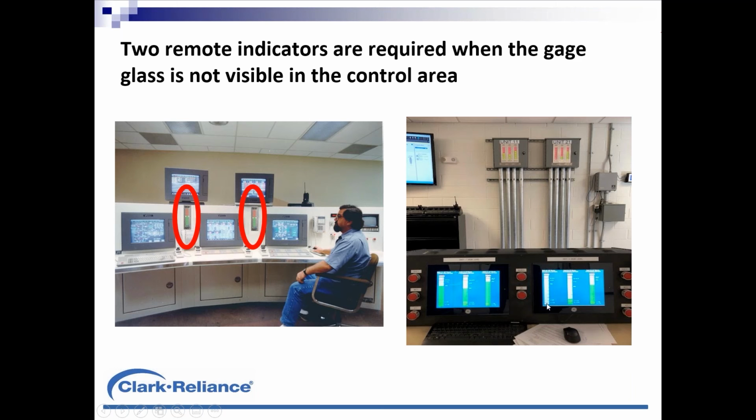Now, this 4th drum over from the left is empty, showing dry, but that unit was out of service at the moment we took this photo. But again, if I were in that operator's chair, I got 2 different technologies for each drum, and they're all reading comparably. So here again, high confidence in how these level transmitters are operating. And these screens never change down below.